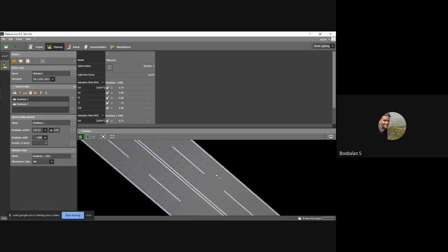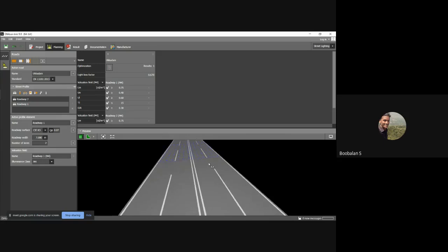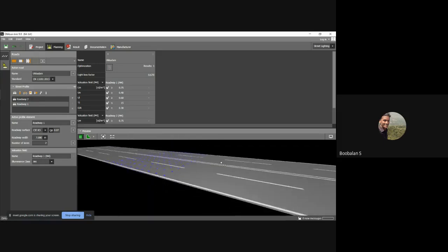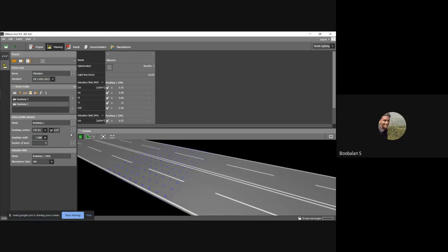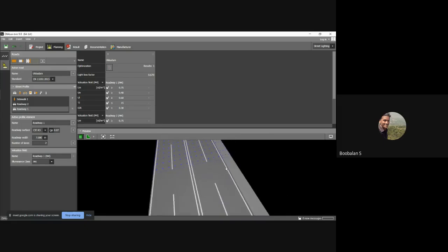So you could see now both highways, right? You can create them easily. That's why I already told you that this is somewhat a powerful software, and it makes 3D rendering easy also. So now I just need a sidewalk, that is called a pedestrian path. Just click on this human eye symbol. Now on my right side, a pedestrian path is getting created.